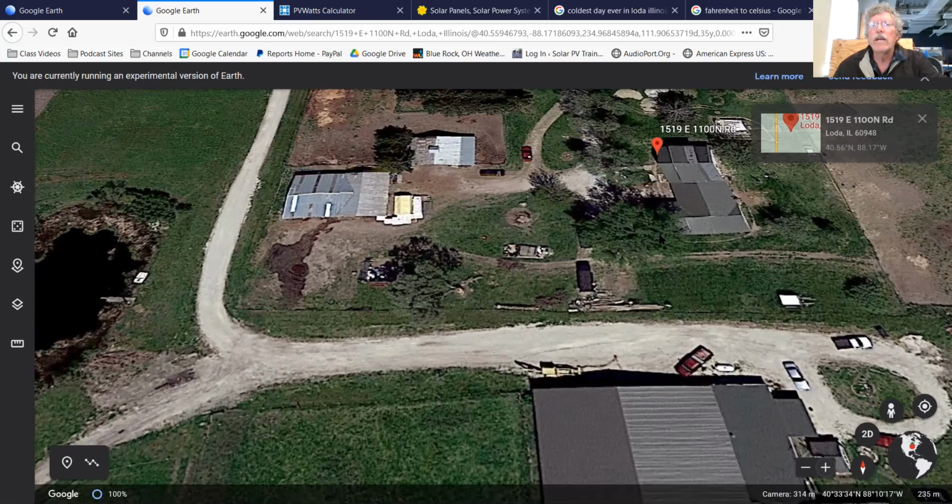And then I can put it at whatever altitude or angle is going to be ideal because I don't have to worry about the roof. So that's usually at this latitude. I find this is at 40 degrees north latitude. I get that down here at the bottom. So you're going to find that the angle is going to be somewhere between 28 to 35 degrees. So if we say 29 degrees, that's going to give us pretty good numbers there.